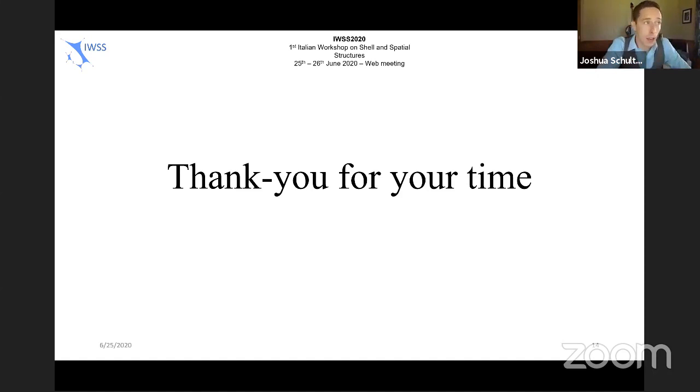And then the other thing that you have to take into consideration is you get rolling shear failures as you start to thicken those out. And so at that point, you've entered a new failure mode. And so there is a limitation really at the same thickness. You wouldn't want to go thicker with that.